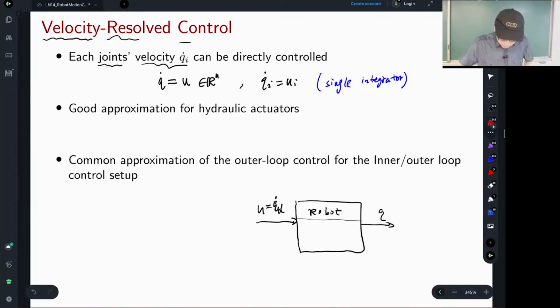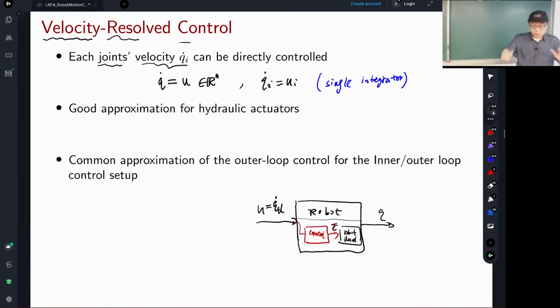If this bothers you, you should think about this. Okay, this is what I send to the robot, but inside the robot, there's some kind of internal controller that we don't care about or don't have any control over, right? It tells the robot the current in the joints. This is the physical plant of the robot. The actual robot plant then moves, okay? But we don't need to worry about that. Let's assume that joint velocity is all we need to provide.